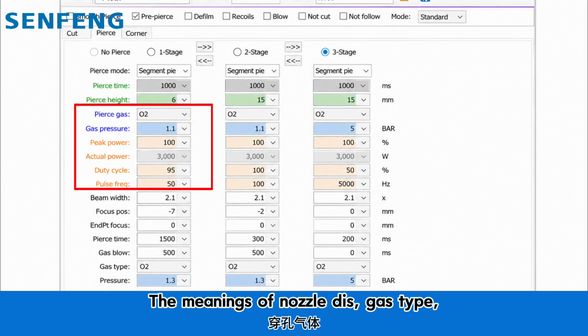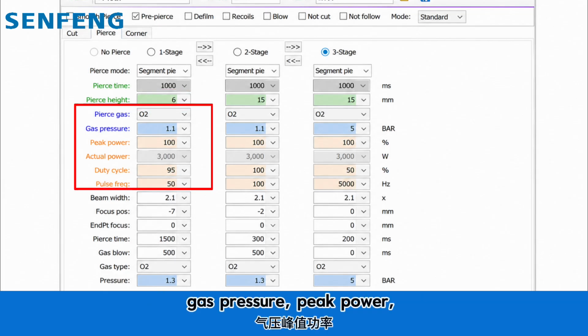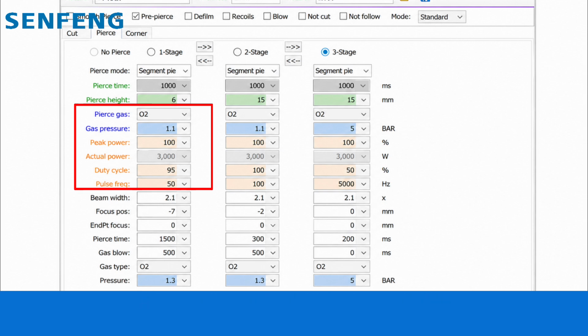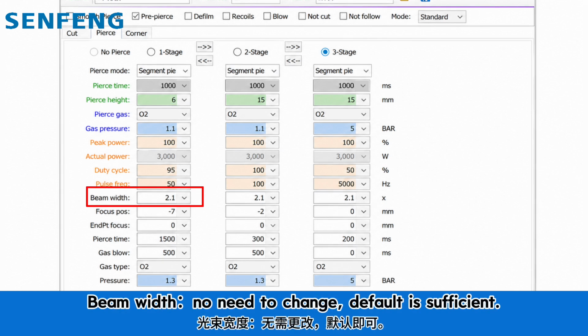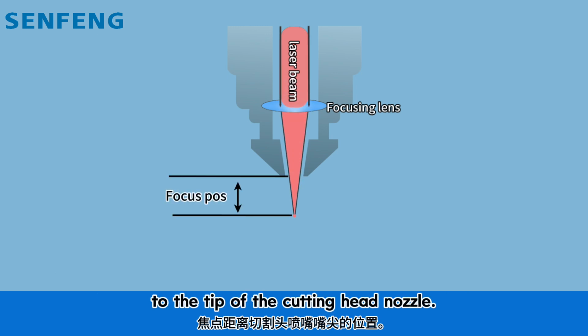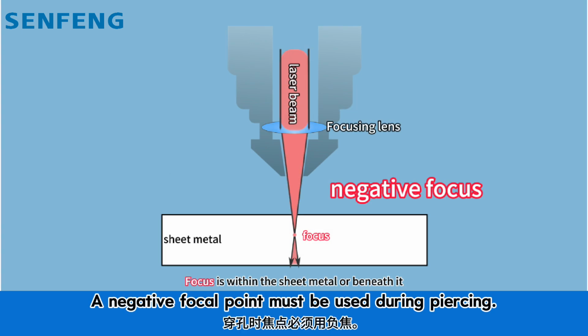The meanings of nozzle distance, gas type, gas pressure, peak power, actual power, duty cycle, and pulse frequency are the same as those in cutting parameters. Beam width. No need to change. Default is sufficient. Focus pass. The position of the focal point relative to the tip of the cutting head nozzle. A negative focal point must be used during piercing.